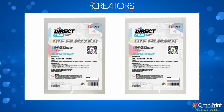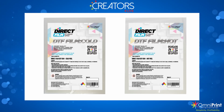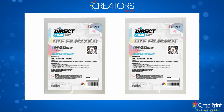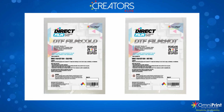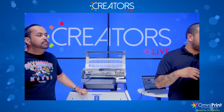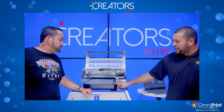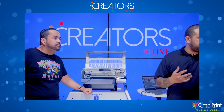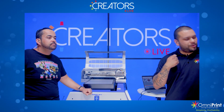We have the option for hot film. We also have the option for cold film, so whichever one you prefer. The difference is that with hot peel, as soon as you get it off the press, you're able to just peel it right off, which really means faster production. That's why we have this heated platen, which allows us to preheat the ink a little bit and print a little bit faster, and it allows us to rip it off right away.